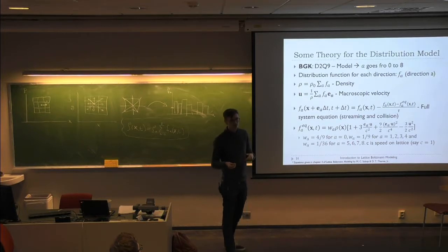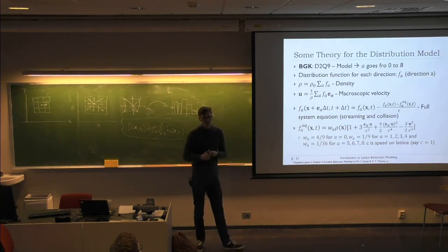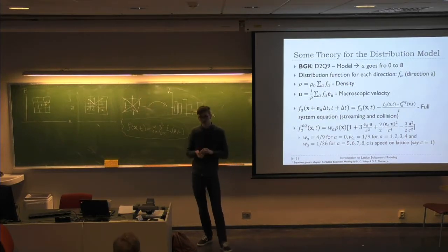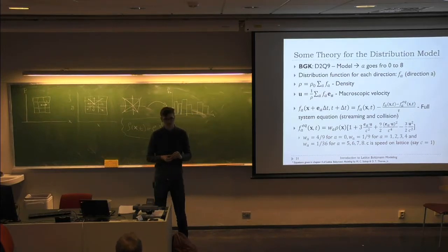And trying to simulate that using a finite difference scheme, it's very hard. If you have a shock, like you would have in an incompressible fluid, a shock front, like when you're at home and you have the sink and you close it fast, you can feel this dunk, a water hammer. You get the shock front. That is very hard to compute using a finite difference scheme because of the way we derive it. You're going to get this numerical diffusion.